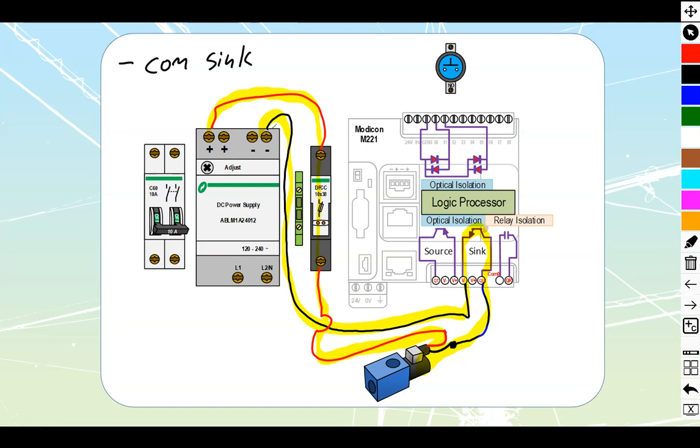This one, however, does have some dangers. Once again, the danger is always going to be prevalent whenever we have a grounded negative on our DC. Let's follow that through, and what we're going to do is accidentally ground this cable over here. If this cable were to get crushed and the negative were to get crushed up against the shield around the outside, if the shield is grounded down or crushed inside of a pipe or cut, whatever it's going to be, if we end up with a fault on the negative inside of here, what we'll get is continuous unwanted operation of our load.